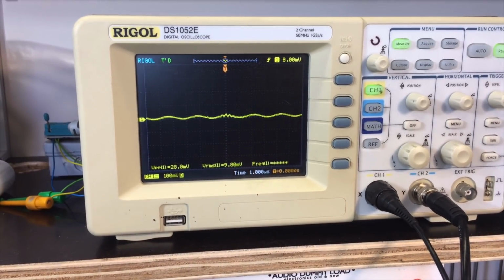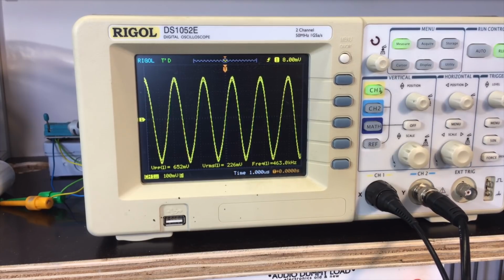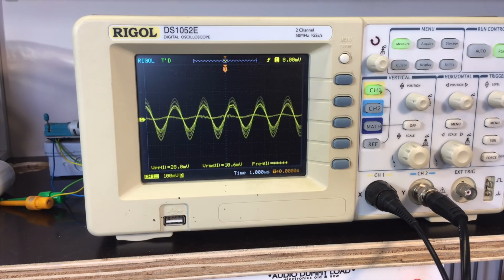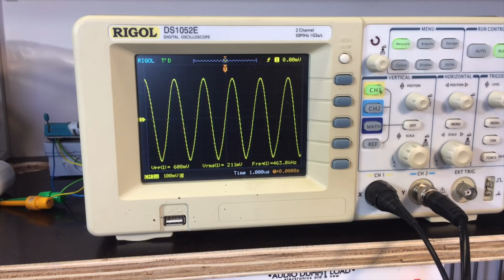Now this point is very finicky. I'm doing it with a spiked probe, which is not screened, so a bit of noise gets in there. Not easy to get it. There we go. And the one I need to adjust is the one just below it.